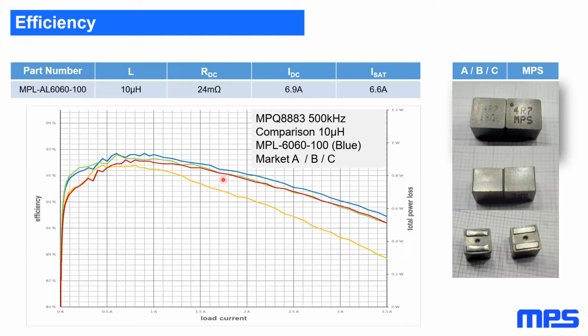I know it's very difficult to measure the AC losses. So the core losses are very difficult to measure or to calculate. And if we calculate, at the end on the real system, the numbers are going to be different. That's why my recommendation is to have a comparison like I did in this case, because there you see, under your specification, under your device, and using exactly the same setup as I did, the difference in performance from each vendor.